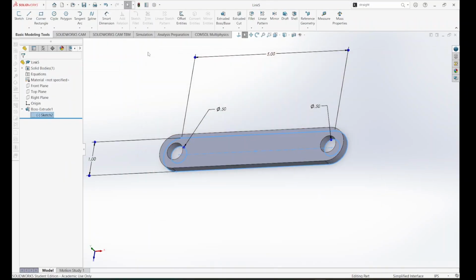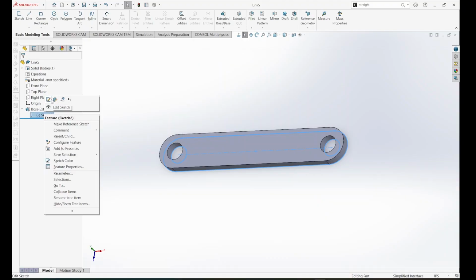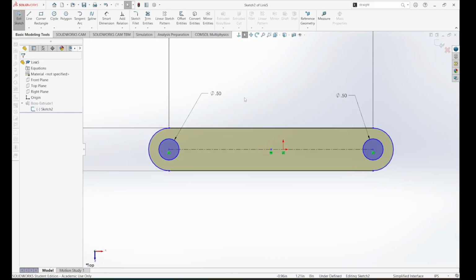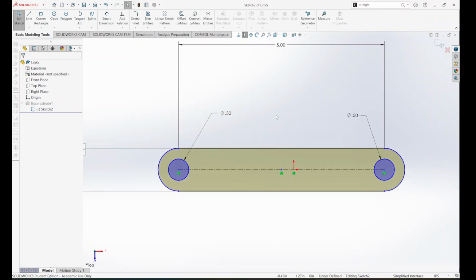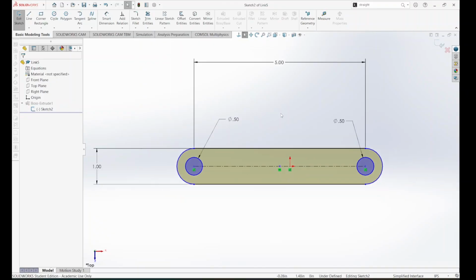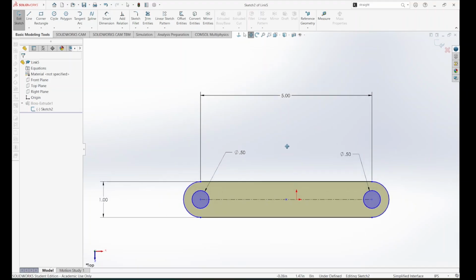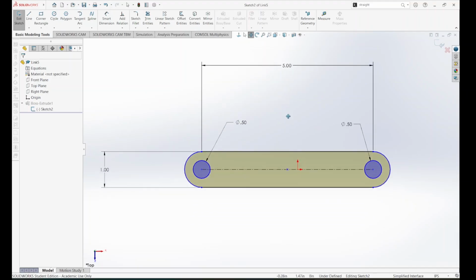And now finally, we're going to make the smallest link. So let's go back to Sketch, right-click, Edit Sketch. And again, here we might use our Pan tool or just zoom out. If we zoom out, we can also do Control and that middle mouse wheel, press that down to drag. So that way we're panning. If we took the sheet of paper and just pulled it towards us.